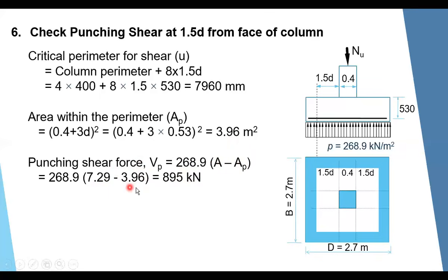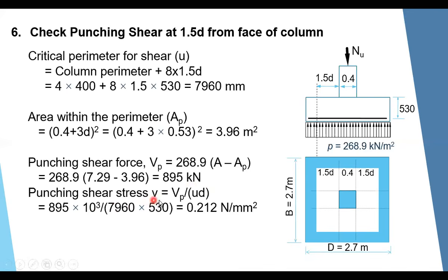Okay. So once we have calculated this punching shear force, we now need to get the punching shear stress. A stress equals a force divided by area. So the punching shear stress, v small, equals V punching divided by the punching shear area here. It will be the area at this perimeter. You can see here that this area will have the plane of punching.